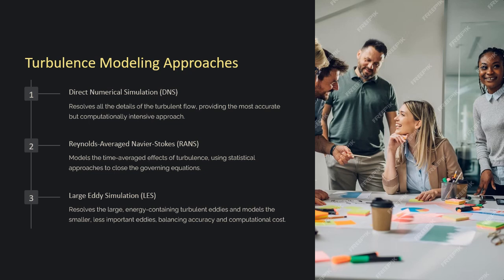Moving on to the turbulence modeling approaches. Firstly, we have direct numerical simulation, which is DNS. It resolves all the details of the turbulent flows, providing the most accurate but computationally intensive approach. Secondly, we have the Reynolds-averaged Navier-Stokes, that's the RANS, which models the time-averaged effects of turbulence using statistical approaches to close the governing equations.